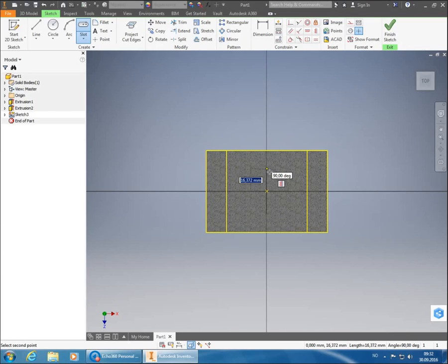But we are starting off from the center and going to one side, so we do 30 divided by 2. So then we get half the length for ours. Again, I haven't locked it in place, so just to be sure, I can press my tab button to get the padlock in place there, and then it actually shows the dimension of it. 30 divided by 2.